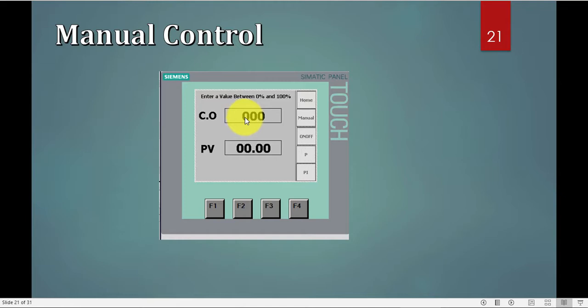In manual control, I have to control the control output in order to keep the PV at a certain set point in my head. There is no set point in the manual control. You have to remember that. I repeat this in every manual control because a lot of students make a mistake with this. In manual control, there is no set point, the set point is only in my head. So I will control, I'm the manual, I'm the controller. I'll change the control output till I get the PV to the value in my head, which I will call it set point in my head.